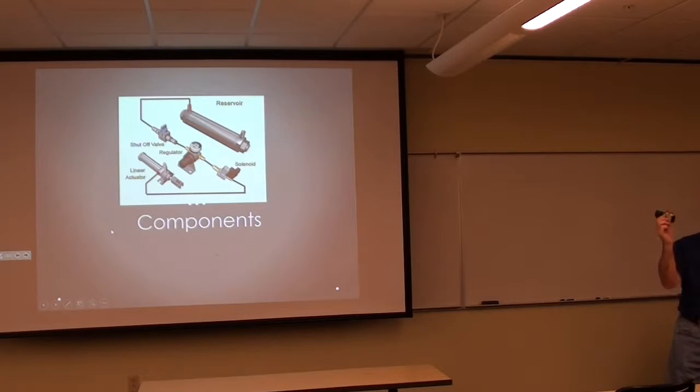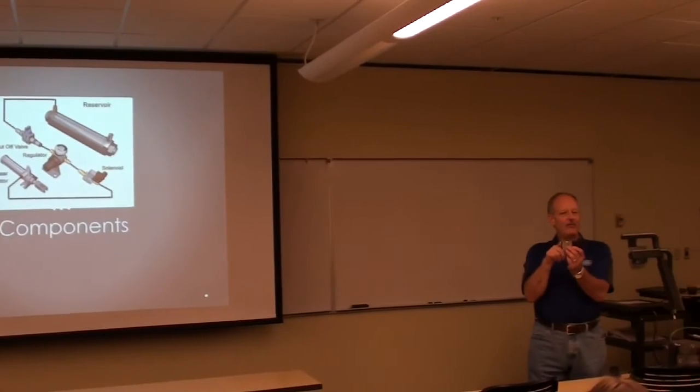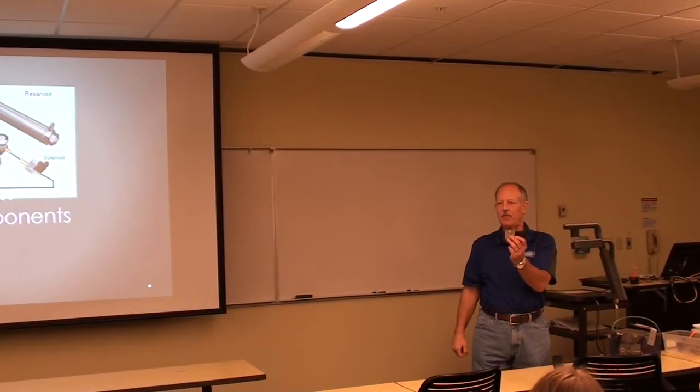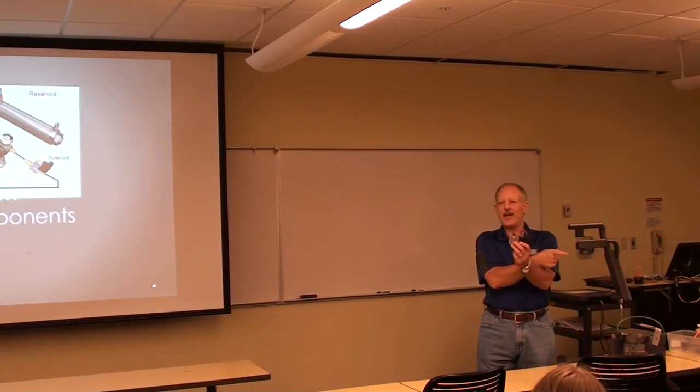Alternatively, if I have 2 solenoid valves, and I'm trying to hold my robot up, like last year, on a dual solenoid valve, if I de-energize both of them, what happens to the valve? It stays where it's at, right?